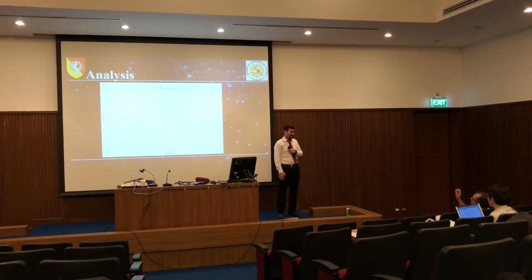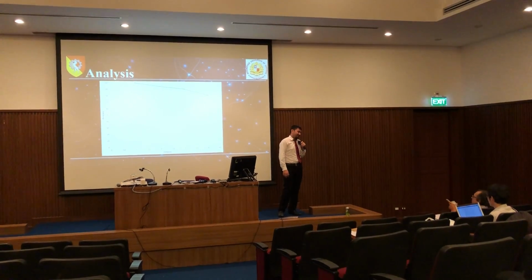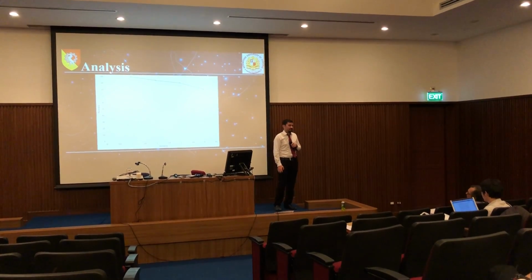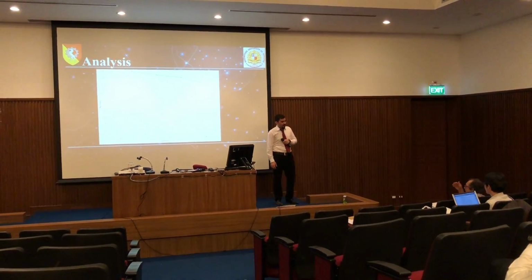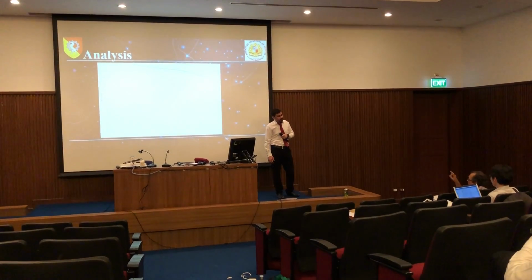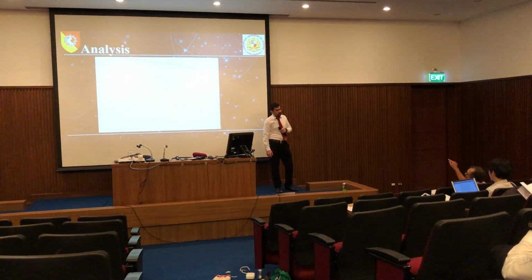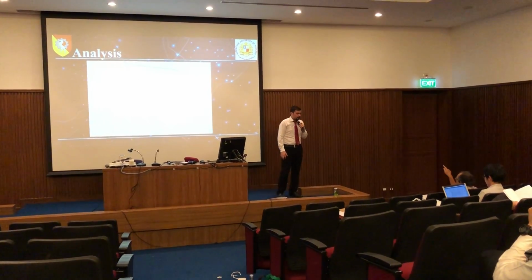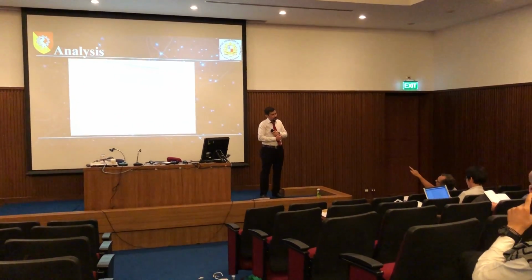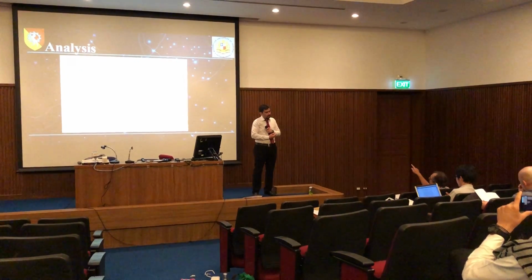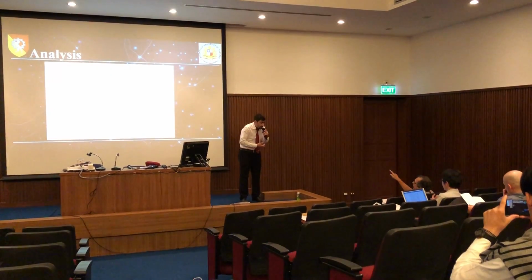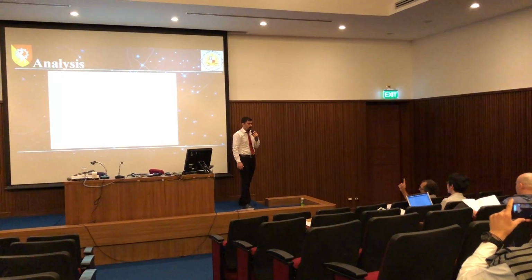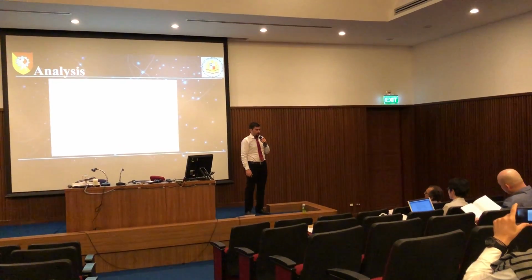There's no depth perception. You've got no stereo. It's effectively a 2D view only, and you've got no rangefinder. So you've got no way of knowing from that picture how far that object is from the camera. Yes, that's unknown. So when it moves 1 centimeter in your frame, that could be anything. It depends on the distance. It can be anything, except at 1 meter distance. Yes.